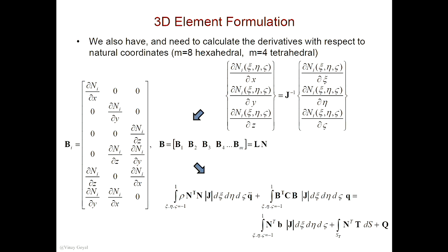So I know the Jacobian. I know this calculation for every shape function. I know B bold completely. They're all in terms of psi, eta, and zeta. Now I'm primed to substitute that in here. Now I have B bold, because I've calculated that. My dV's are already done. I know the Jacobian, I know the determinant. All my integrals are from -1 to 1. I can use Gauss quadratures to evaluate these integrals. And then I still have to tackle this surface integral, which can be done quite readily.